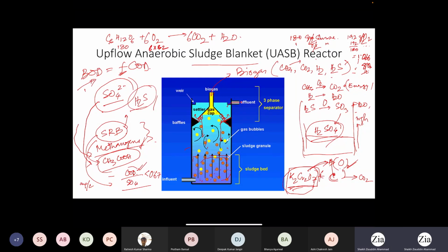So if it is readily or biologically degradable, then you will get a higher value of BOD. So that's why the fraction F value could be 1, or maybe the F value would be a little bit less than 1. Now, when you get any wastewater, you first characterize it, meaning you do all this analysis: different ion analysis, oxygen, the BOD value, COD value, nitrogen content, sulfate content, different other ions, and then you get some idea of this ratio, the BOD COD ratio.